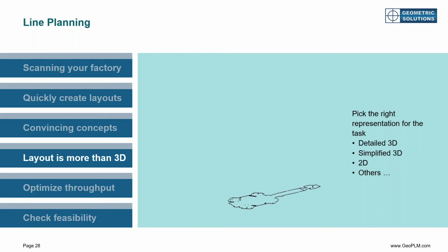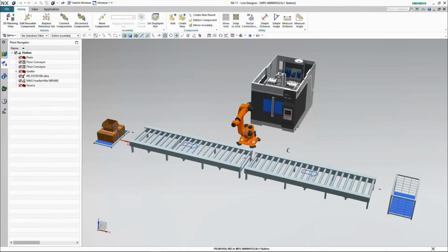Depending on what I'm trying to do, I have had many 3D layouts that I've done, but I have 2D views of everything on the floor because I don't need the 3D. I'm just looking for bolt hole patterns on the floor where I need to put in anchors. So I can make a layer or a drawing that has just the anchor points, but I have just 2D sketches, outlines of the product without any details, so I can see what's going on.